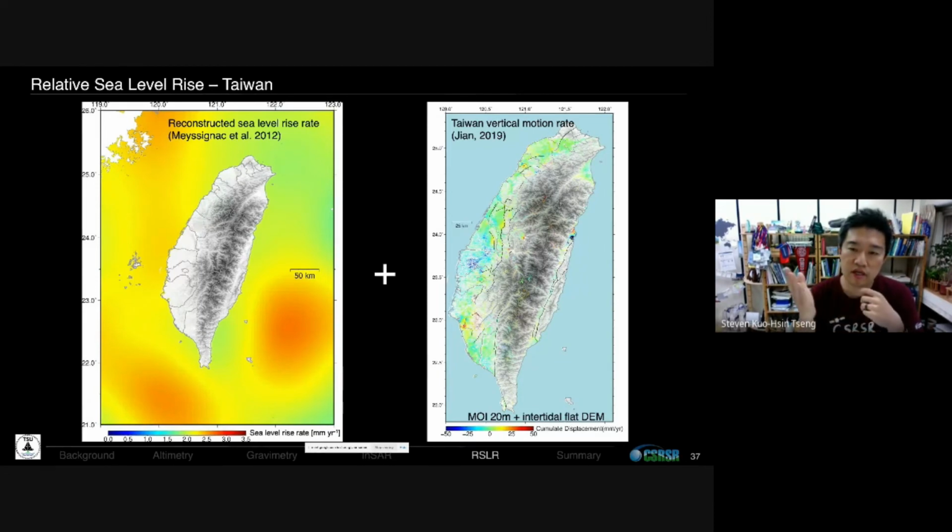For most open source DEMs like SRTM or ASTER DEM, you won't have a good elevation model along the intertidal zone, which means that near the boundary of the land and the open ocean, there's a stair. It's very weird, but it happens in all the products. Our lab has constructed an intertidal zone DEM to fill the gap. However, if you have a good DEM, you can make this simulation as well.